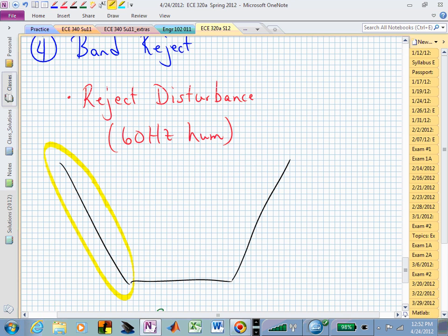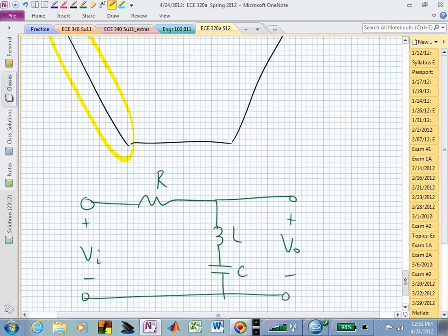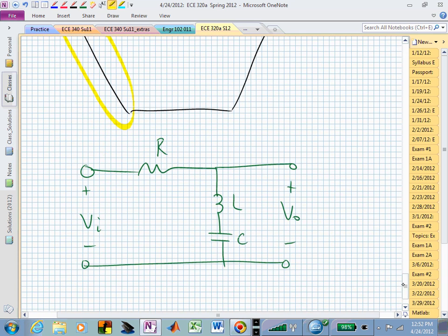What's going to allow us to go flat? A zero, because now that's reducing our slope, and now we want to reduce it even more or make it go the other direction, and we put in another zero. So there are ways of cooking these up in order to create different filtering behaviors.